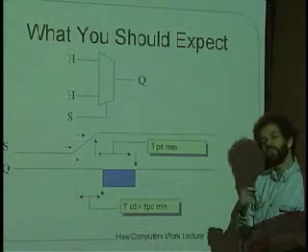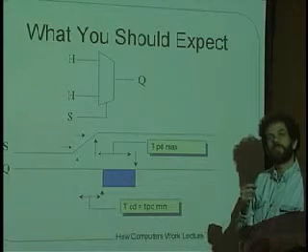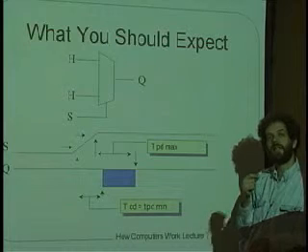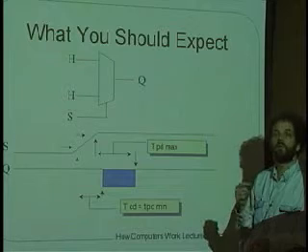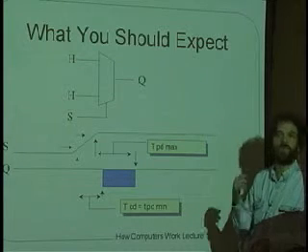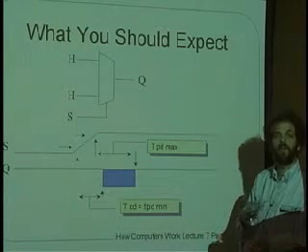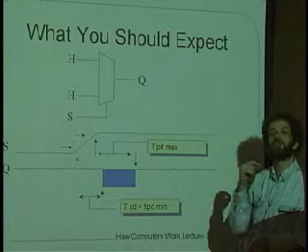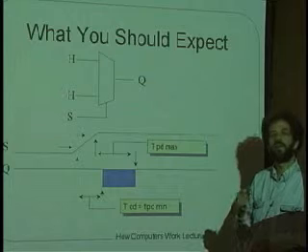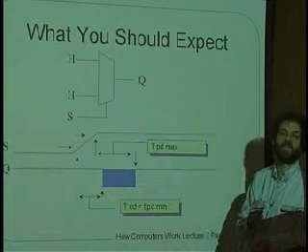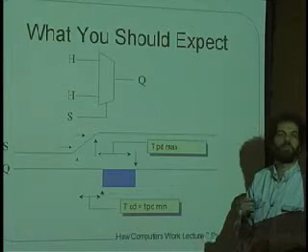Whereas with propagation, remember how that was used. That was used to figure out how soon can I clock the circuit again and make use of the output. And there the question is, over the entire temperature range, over all kinds of different parts, things like that, over different data, what's the longest that it could take for the new valid value to get there, so that I know when to wait until I clock it the next time. So that's why that's in general measured in terms of the maximum.